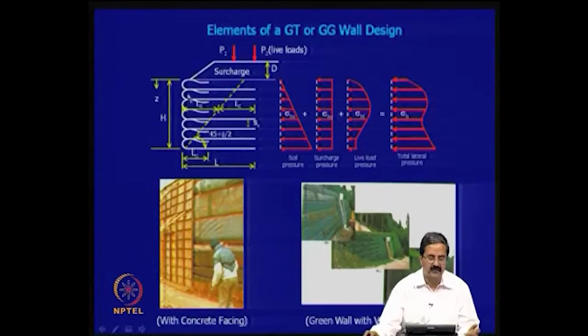And in some cases, for permanent applications like retaining walls with a lot of loads, we cannot have that. So, what we go for is a concrete facing. It can be any other facing, because the advantage of the facing is that you can design it in such a manner that the earth pressures, we know, are very minimum here.